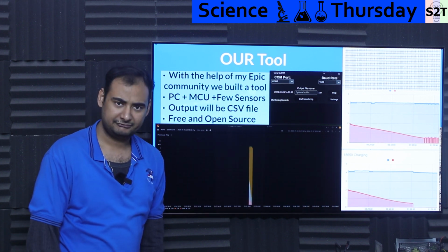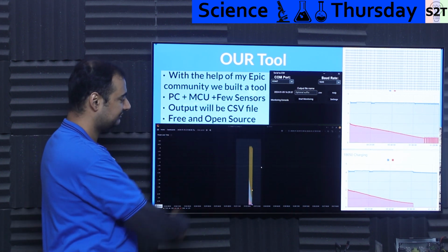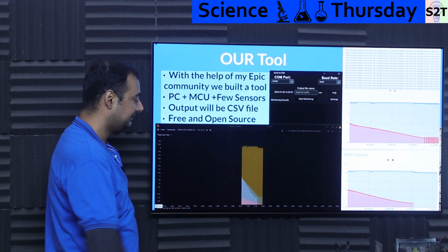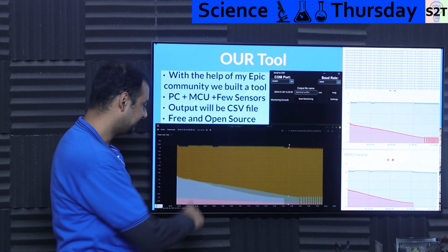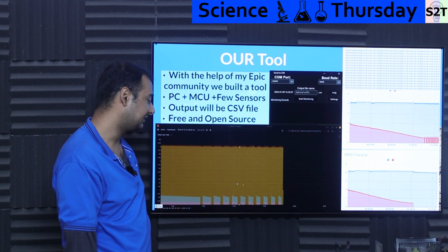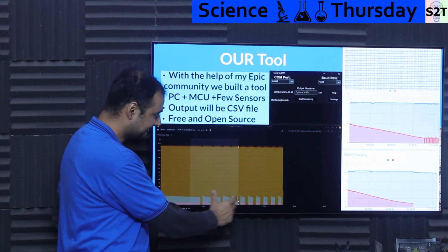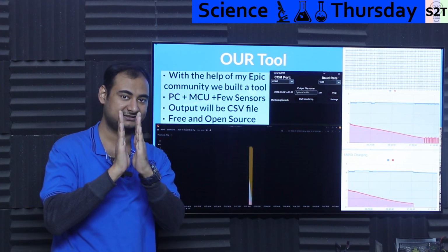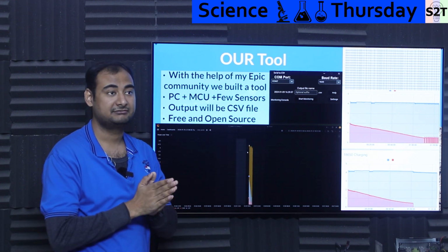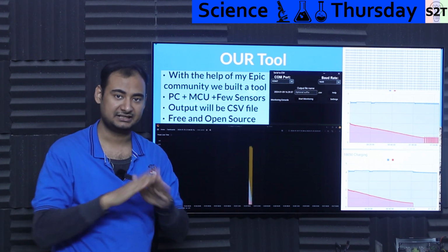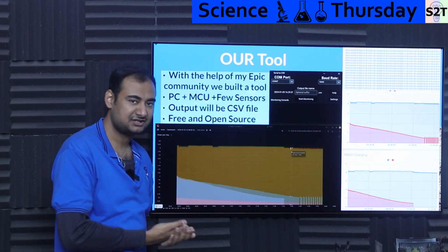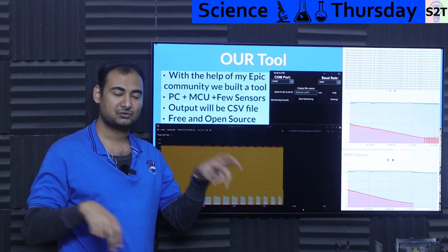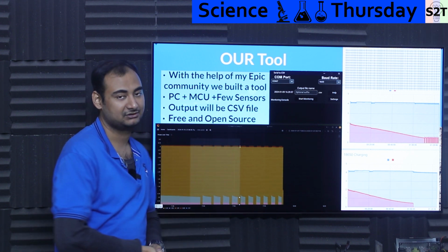However, if you are feeling bold, you can dump that data into Grafana. This is in Grafana, and you can zoom in. That's the main benefit. Here you can't zoom into the graph, but here you can zoom in interactively. See, now I can zoom in and see that the oscillation width is shrinking. So there may be a chance that if I had recorded for longer, I may have noticed that it flatlined. Again, is it a cell thing, or is it a charge controller misbehaving? I can swap things and test it. That's why we need this sort of tools.